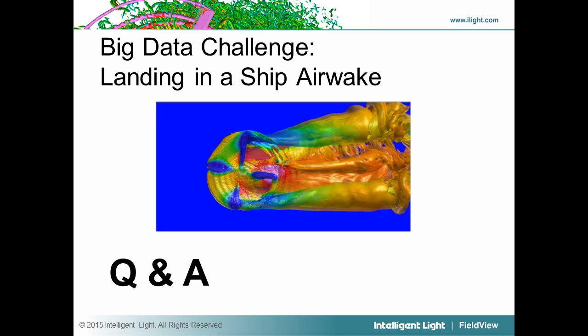A couple of questions here. First one is for you, Jim. So how do you create boundary surface extracts in Visit? Visit doesn't really have the notion of define your mesh and then tag things as boundaries. So what you do is you create another mesh that is just your boundary surfaces. In this case it was a 3D case, so you define what your topological dimension is.